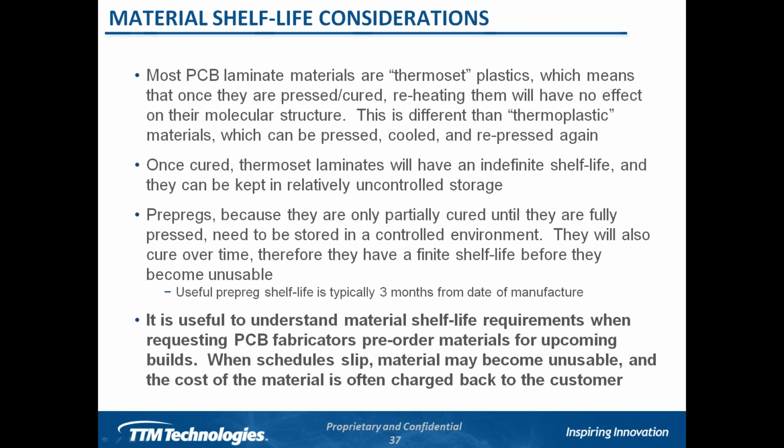On the prepreg side, because the prepregs are only partially cured when they arrive at our facility, and they stay partially cured until they are fully pressed and cured, they do need to be stored in a controlled environment. Controlled environment means controlled humidity, roughly around 50%, and a temperature that is not going to have these things self-cure, because prepregs will self-cure over time. Because of that, their shelf life is finite, even if they are kept in a controlled environment. And useful prepreg shelf life is around 3 months from date of manufacture.